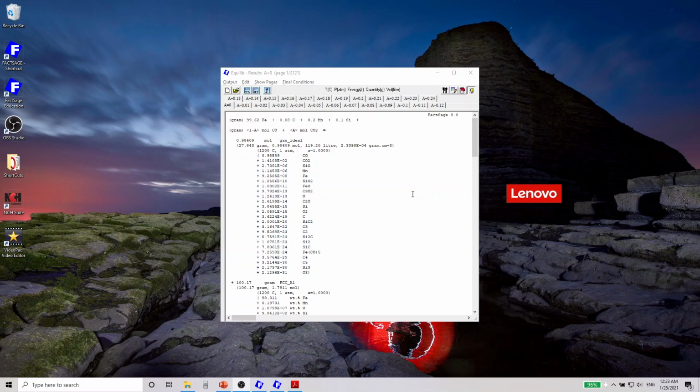After clicking Calculate, FactSage gives us the results. Now we want to plot to see, for the target carbon compositions, what is the variation of CO2 amount in our gas that is needed. So in order to do that, we have to go to the output, use left mouse button, click on it and then plot results.